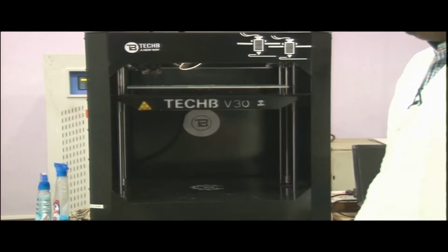Okay, about FDM and SLA. FDM machines produce products with precision, but the precision level in SLA is higher. Higher resolution objects are more possible to produce in SLA because resin is there. The resolution is primarily determined by the optical spot size either of the laser or the projector, and that is really small in SLA. In FDM, it is the printer resolution, which is a factor of the nozzle size and the precision of the extruder movements. That extruder we will discuss in this demonstration as well.